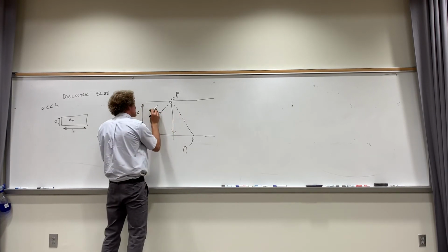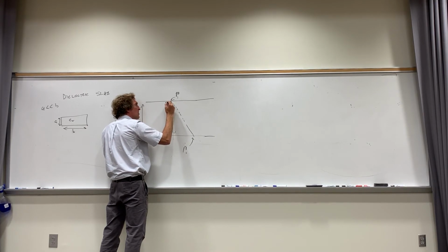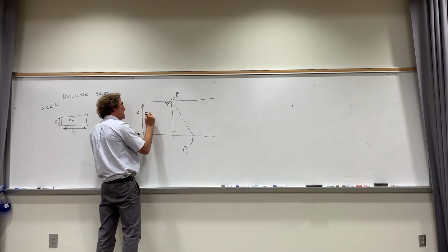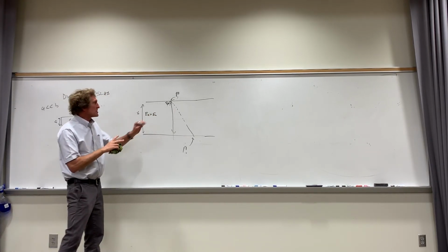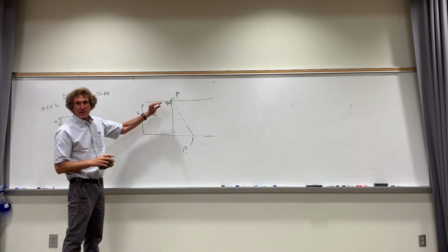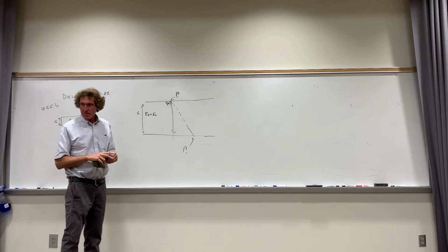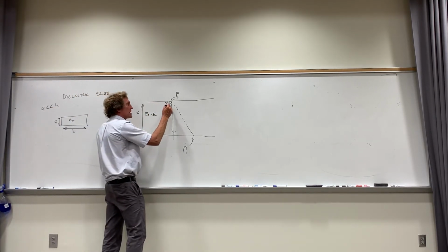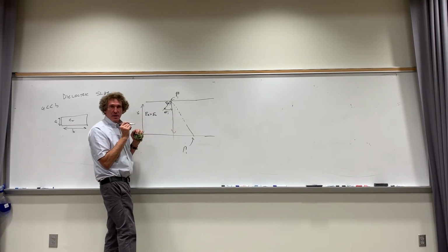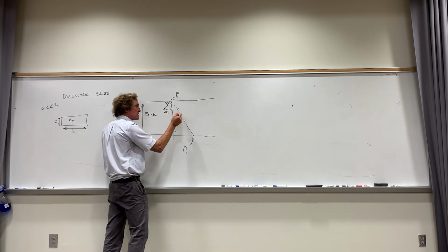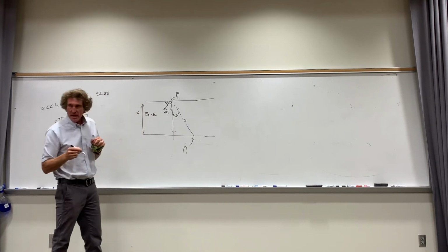Dr. Whitworth says that he's going to assume the field just before it hits there, that's the incident field. He calls it EA, and he says let EA be equal to some E naught. And he didn't say if it's TE or TM, if the field's sticking out, that would be TE, or if it's in the plane of the board. For our purposes, it doesn't matter yet. The wave's direction does, and it comes in at an angle theta incident. Just write this down. It reflects off, here's the reflection, at an angle theta incident as well. I think y'all can imagine that, all right?